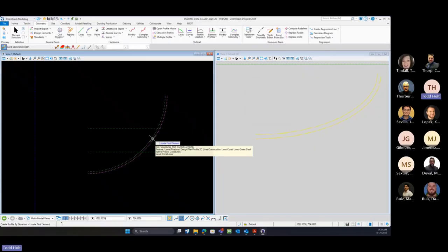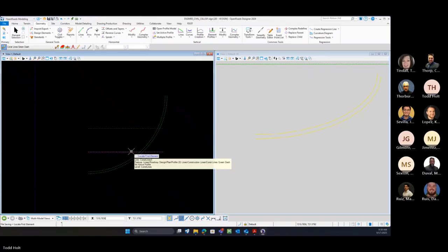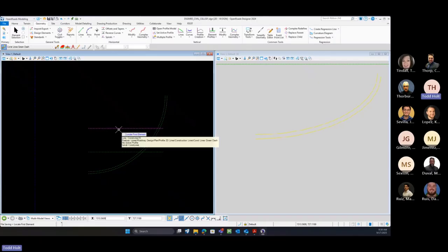So I'm doing that because when we pick those, we're going to inherit the profile from the elements that we put in. So this is going to allow us to build that 3D geometry that we have in to those civil cells. And maybe this curved back top or the sidewalk front is a 2% slope from that sidewalk, and the front back sidewalk is 2% on.